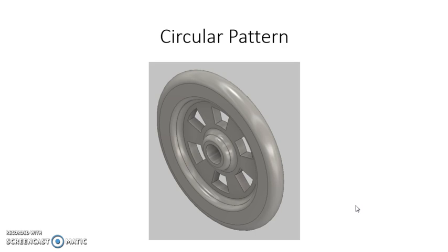The next step is then to circular pattern all the way around with that cutout. You're going to have 6 of these that go around the rotational axis. Any of these cylinders is fine because they all have the same center. You're going to have a wheel that looks like this. Almost done. We need that little piece that sticks off the front, right?